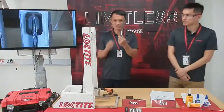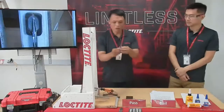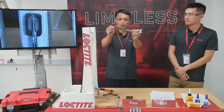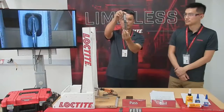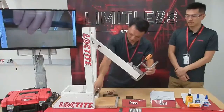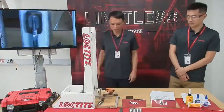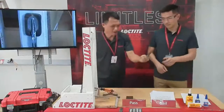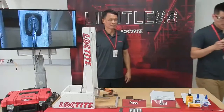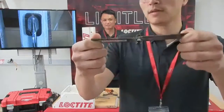So we can proceed with a similar test on the joint by the other assembly method. The second one is the joint done by the mechanical fastener. As you can see, we have 2 M4 fasteners for the assembly. Then we put it onto the impact tester to see the impact strength of the assembly. Can you tell us what you have seen from the specimen? I think it's still good, but I can see that the placement between the 2 substrates has shifted, like this.